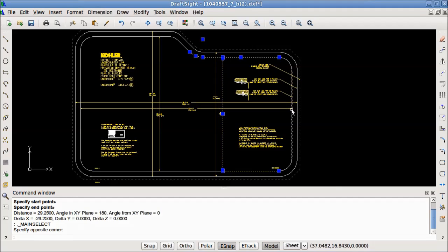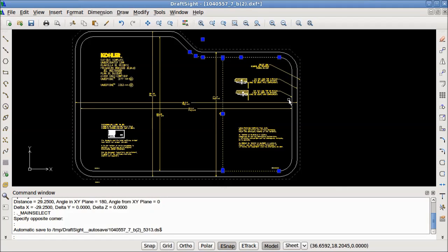As you can see, this dimension line overlaps with this section of the cutout line, so it'd be easy to inadvertently select lines that I don't want to use to create cuts in the CAM program. So to make this easier, we will clean up the drawing using layers. Layers are a way to organize entities. For example, it is common to have dimension lines on a separate layer from the drawing, and comments on yet another layer. The visibility of individual layers can be changed.